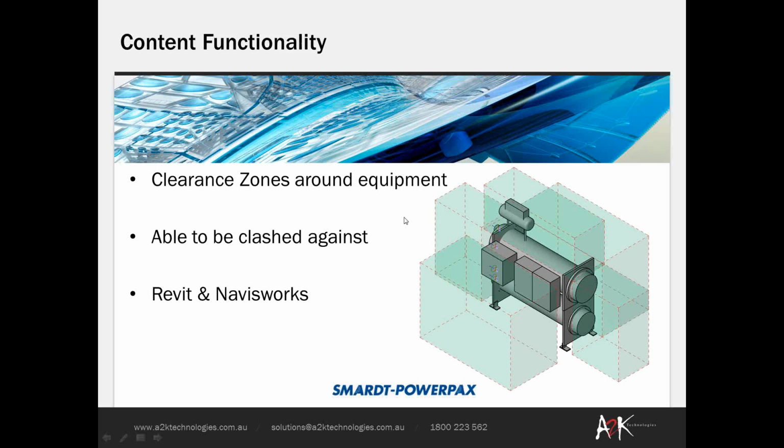And these can be turned on and off. Okay, so there's an option in all of these families that have these clearance zones to turn them on and off, so they don't have to be on in any particular view. But just keep in mind, if they are off, they won't get exported into something like Navisworks. They do need to be on in the view that they're exported from, etc. Okay.